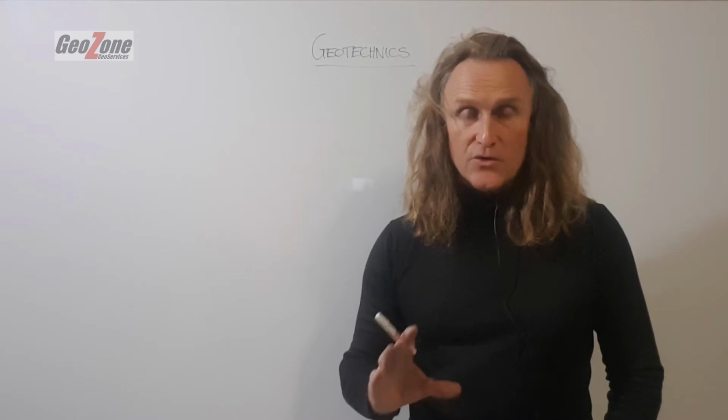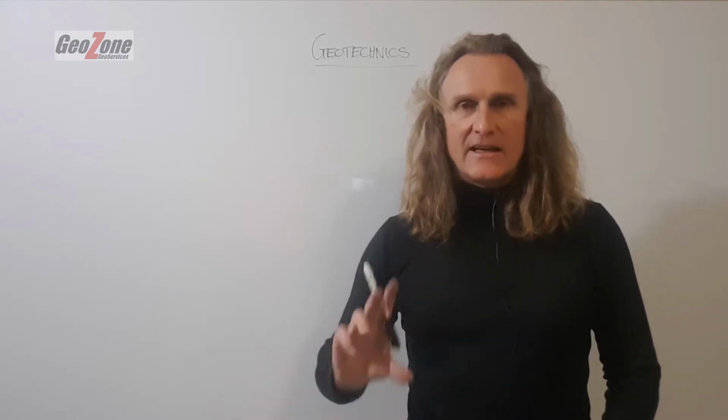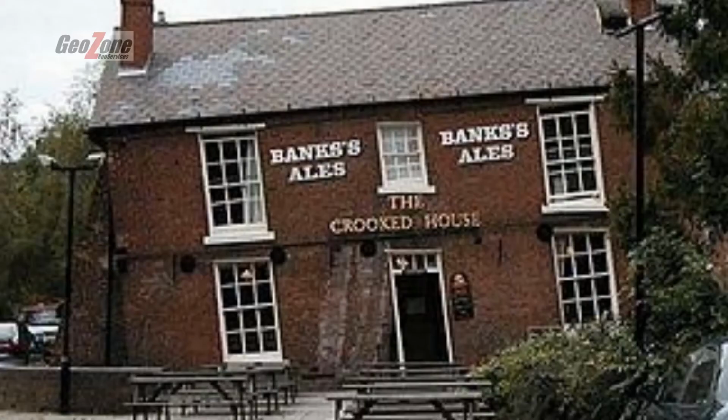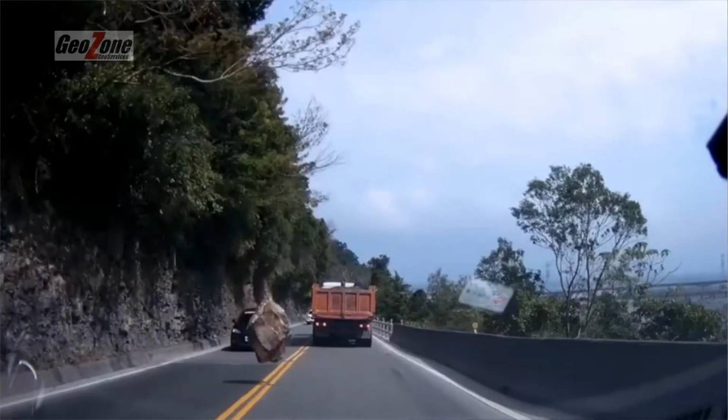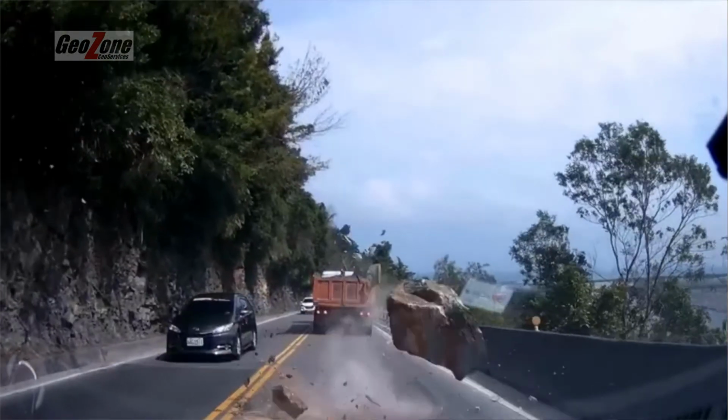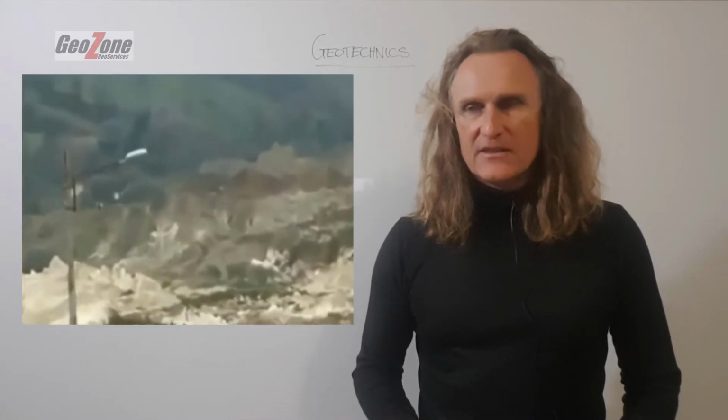Then we have collapsing soils. Wind-blown loess that gets driven by wind can also collapse. We have those in South Africa. Then we get consolidation taking place. You load a clay and initially the weight of the building is carried by the water in the pores of the clay, but ultimately that load will drive the water out, the clay consolidates, it settles, and your building is damaged. We have rock falls, landslides, settlement of different kinds, collapse.